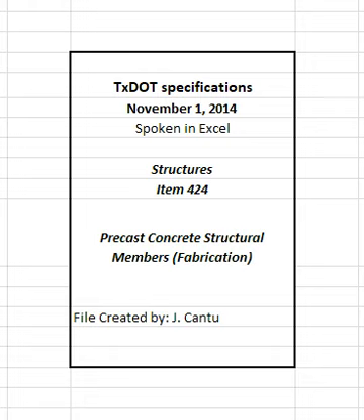Use overlapping sprays, sprinklers, or soil soaker hoses so concrete surfaces are kept continuously wet. 4.2.7.1.3 Ponding method. Use an approved retarder when the air temperature is above 85 degrees Fahrenheit in accordance with the manufacturer's recommendations if necessary to control concrete slump loss and lengthen the time for placing, consolidating, and finishing operations.